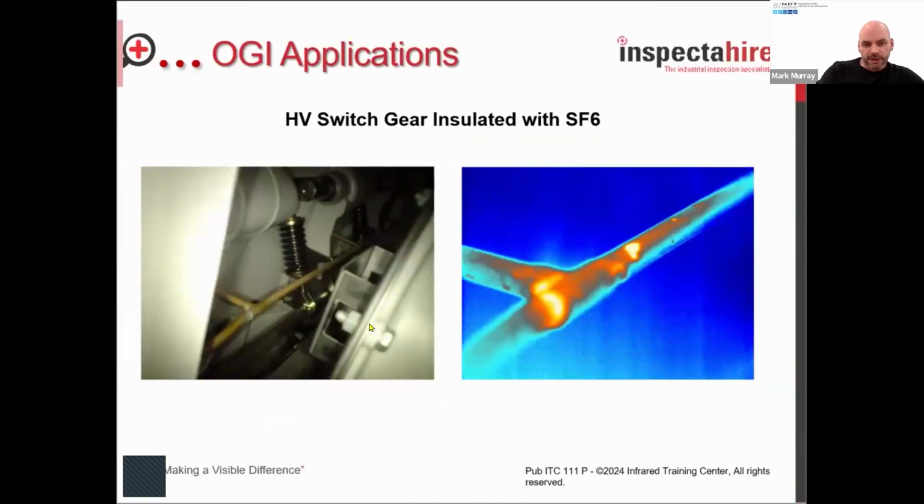So in this example, this was high voltage switchgear, and they were able to remove the panel. They obviously isolated the switch. Now, there was a gauge on the outside of the panel that showed a 0.4 bar drop in pressure over a 6-month period. So it was a very small emission. They isolated the switch and it was given access, a roughly 6-inch opening at either side of the switch, to be able to check this copper system.